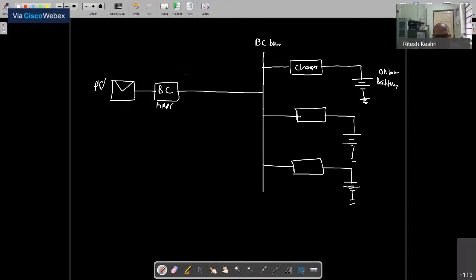Remember that this type of charging station has a limited capability. If the capability of the source is limited, then we say that you design it for 100 ampere. And then each of these vehicles is drawing, let's say, 20 ampere. So 20 ampere, only charging one, is no issue. That is around 5% of that. 40 ampere, 10%, 60 ampere, you can see, so you are increasing the percentage.